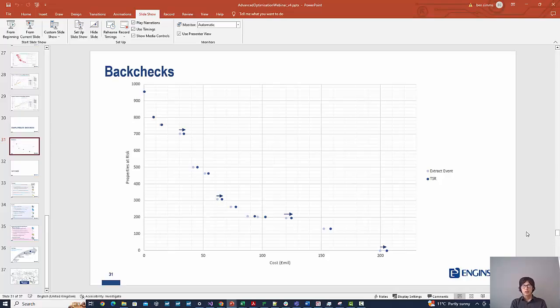On this slide you can see that there is also generally comparable, and there's a fairly consistent offset that might need to be corrected for when you do the back checks. But typically, if you're looking at it on this kind of metric where it's a cost difference to correct for the spills, I think the worst case here was around about 10% of the solution cost. Often you get much closer matches than this as well, more similar to the points you've got in the top left there, where they pretty much directly overlay. I suppose it just depends very much on exactly how that catchment works and how the hydraulics affect things.